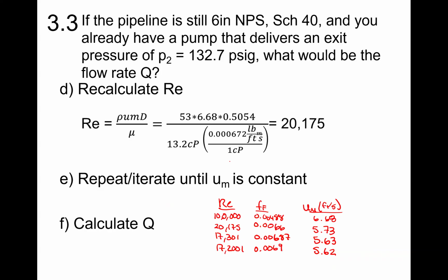I always say that in these calculations, there's other factors that contribute more to error than your own calculation errors and iterations. Like, for example, the roughness of the pipe is not exactly the roughness that you will find on the table. And there's some variability on those, and there's going to be corrosion of that pipe over time, so the roughness changes. All of these contribute to errors in calculations of fluid mechanics that are much higher than getting a little bit of a 1% or 2% error on your velocity calculation. Okay, so that's how you solve this type of problem through iterations.